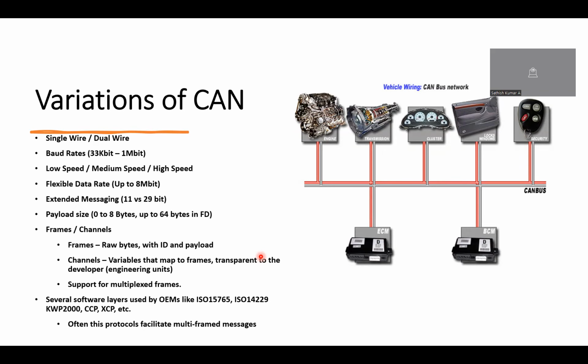And payload size, for payload size 0 to 8 bytes, right? It's the normal payload size for all the CANs. It's exceptional for CAN FD. For CAN FD, it will be 64 bytes.